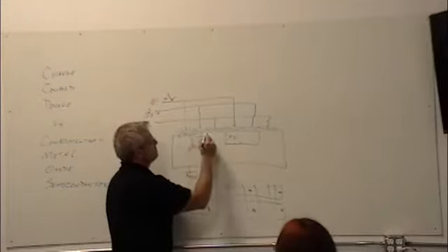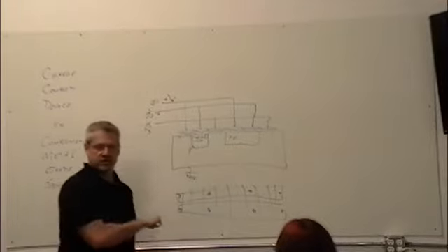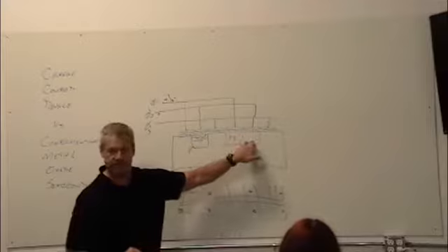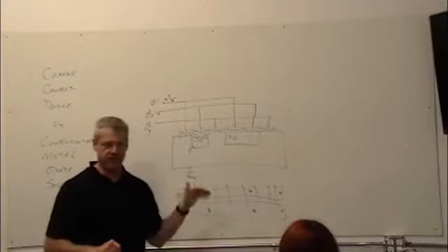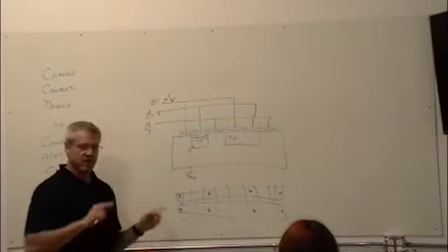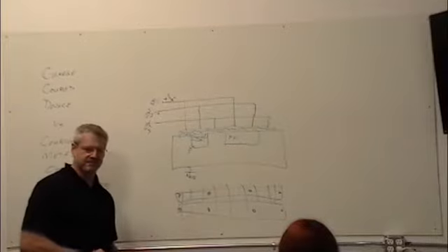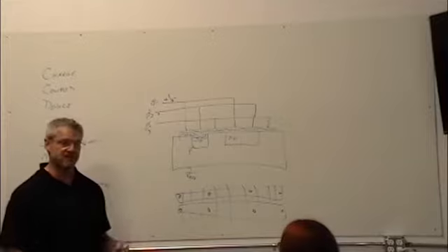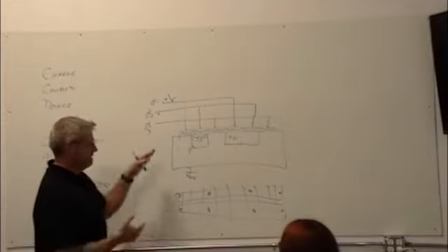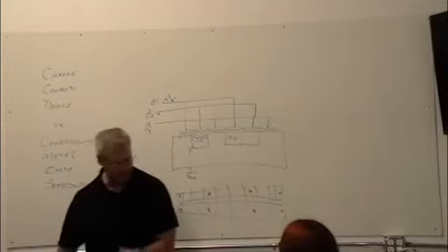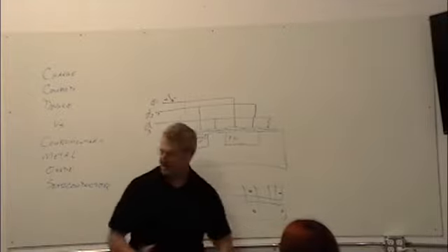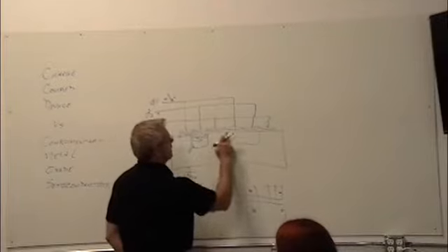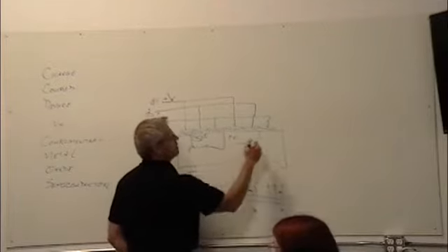And now I've just moved my bucket of electrons from here to here, and simultaneously from here to here, and n times down the row. This is why it's called a bucket brigade device. And you can buy things called delay lines that are based on bucket brigade technology. You're taking a sample of stuff and you hand it over to the next guy, and at the same time you take the one from the one next to you. So what happens here, I collapse this one, now I do it again.